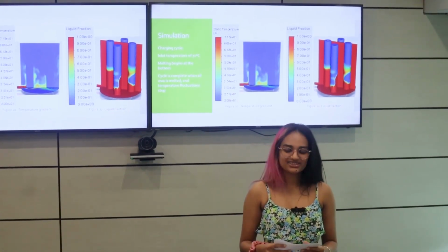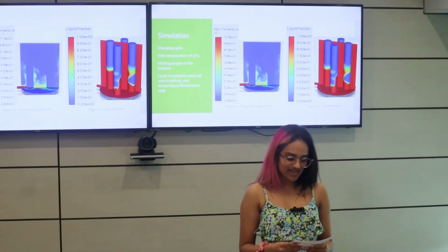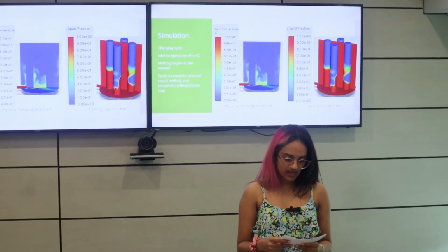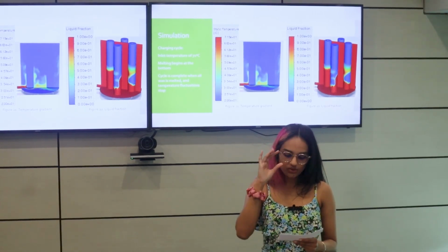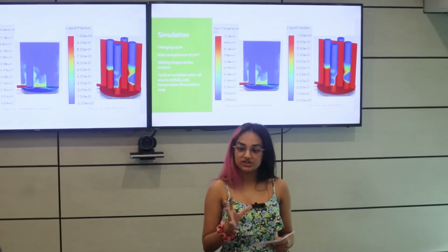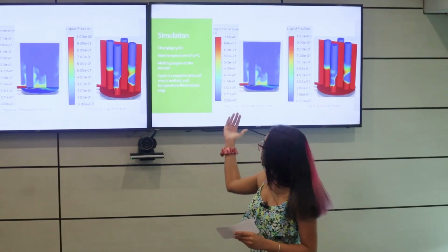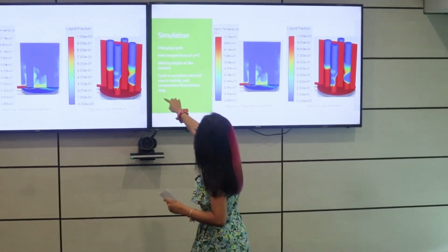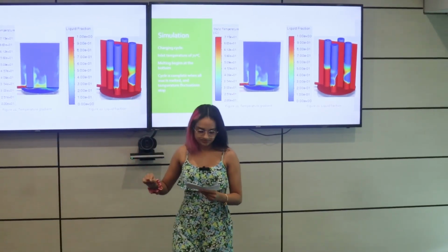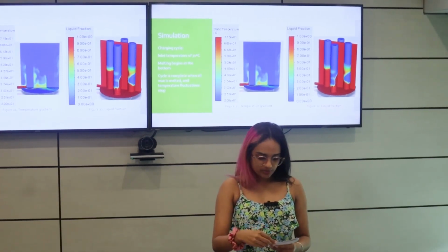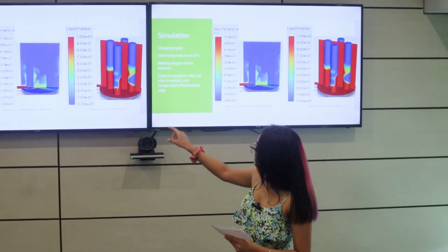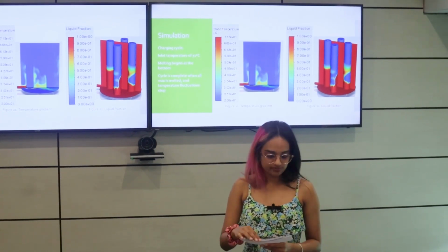On this slide, figure 21 shows the temperature profiles as the simulation progresses. And figure 22 shows the liquid fraction. The liquid fraction is a useful profile as it shows how much of the wax is solid or liquid at this phase. The red areas are fully liquid. So as you can see in this cross section, the red over here would represent the water, and the red inside these tubes is the paraffin wax. From these figures, it was observed that melting begins at the bottom of the tubes. This was expected as the inlet of warm water was positioned at the bottom.